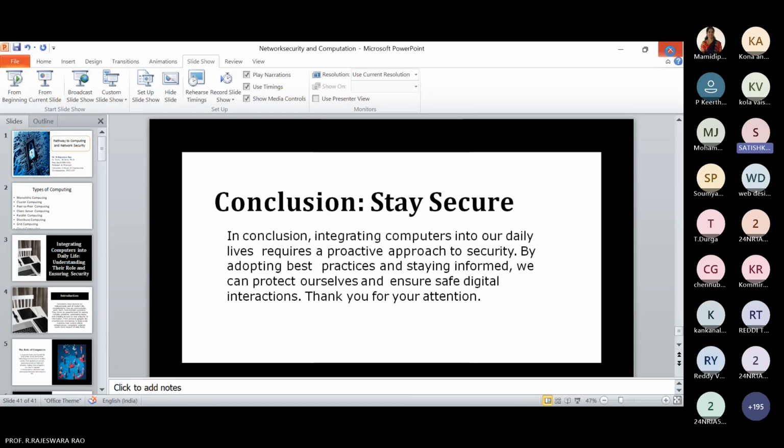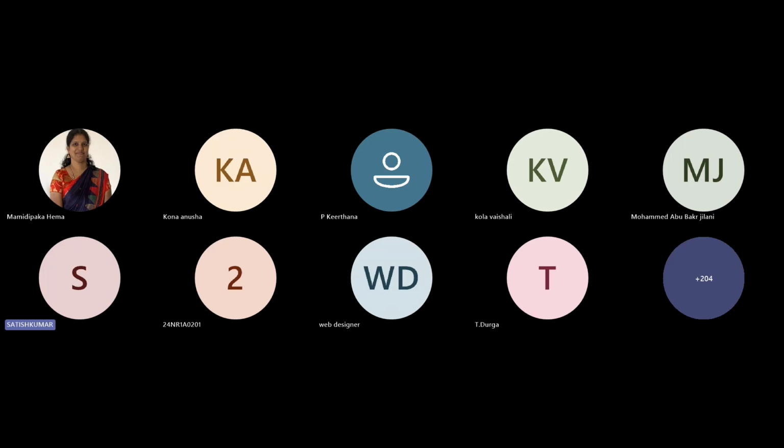So the main components of IoT are sensors, actuators, and microcontrollers. Sensors give the input to the controller. You can see this PIR sensor: when a person enters, it automatically sends the signal to the controller. Once the controller has received the signal, it gives the buzzer sound and the light blinks. So it becomes an actuator, because when a person has entered, we can easily know by using this system.